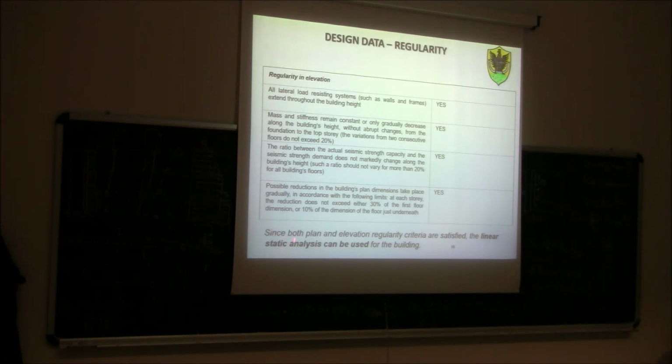So, if both plan and elevation regularity criteria are satisfied, the linear static analysis can be used, which is what we want to use. Because the linear dynamic analysis, you are going to learn next year in the first semester when doing dynamics of structures. Okay?